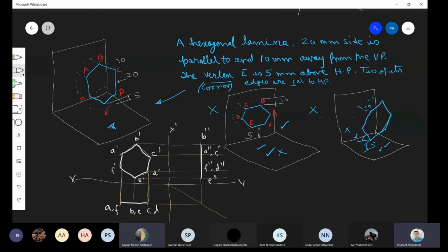Sir, I had a doubt. Yes. Sir, a small doubt in the side view. The triangle part of the hexagon will not come, sir. Look, the A dash F dash and C dash D dash of the hexagon are both a bit outside, right sir? No, they are not, because this is not drawn perfectly parallel to this vertical plane. If you make this perfectly parallel to the vertical plane, you will see only one edge AF. Correct? But sir, above A the B point will also be visible vertically, right? B dash E dash will also be visible, B and E will also be visible, sir.